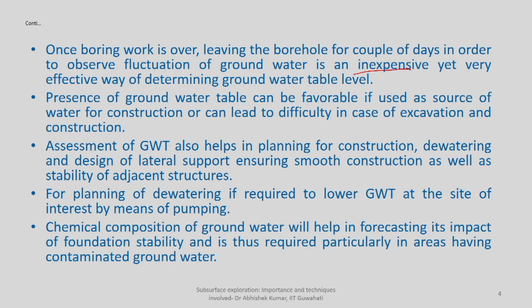Assessment of groundwater table also helps in planning for construction. If you know the groundwater table is very shallow, once I am going for actual site exploration or excavation, then I will make certain arrangements, whether in terms of providing lateral support, or some kind of confinement, by laying some concrete on the sides as well as the base, which will ensure no seepage of groundwater into your construction area.